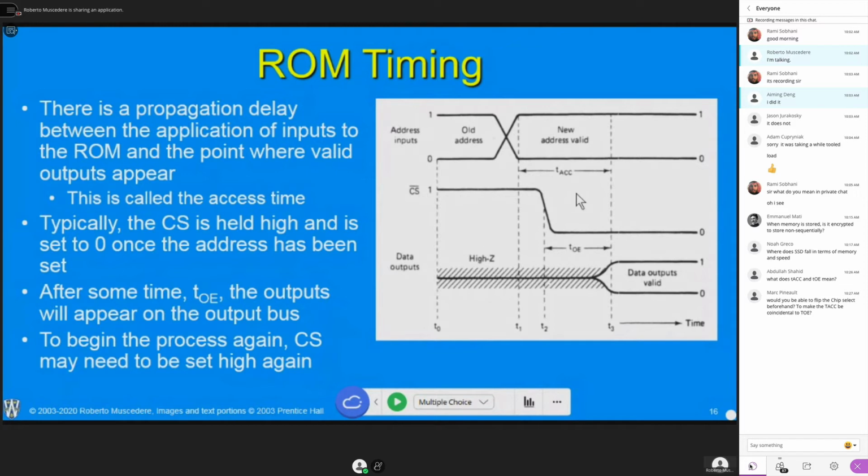So when you plug it in your computer, it doesn't actually start talking to the memory directly. It talks to that little memory chip that has all the specifications stored in it. It pulls all that information out, and it knows how to talk to all the other parts of the memory. It knows all these parameters, so it can interact with it easier, right? It can kind of say, oh, it talks these three different ways. Okay, I'll use one of those, right?